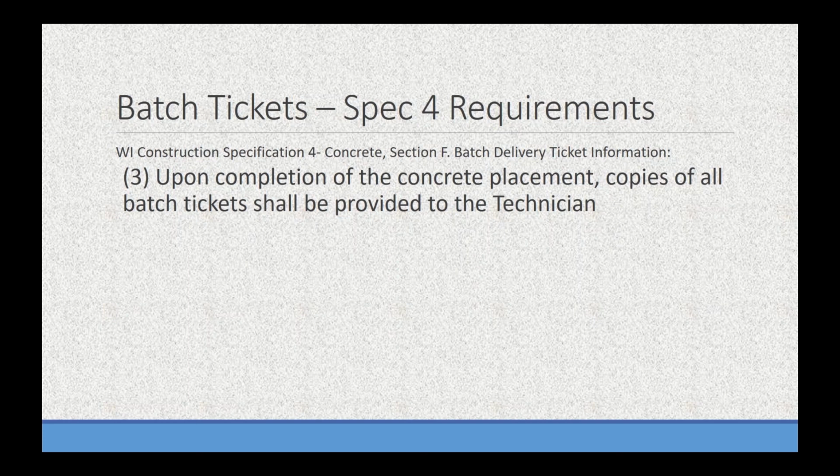And all these requirements, it would be a really good idea to mention these at the pre-construction meeting. Mention these to the concrete contractor. If you have a representative from the concrete supplier, maybe their quality control guy at that pre-construction meeting, you're going to want to make sure to go through the requirements just so they're aware if they're handwriting batch tickets or if they don't typically include moisture percentages, that it's required that they include those on the batch tickets that are going to be delivered to your job.